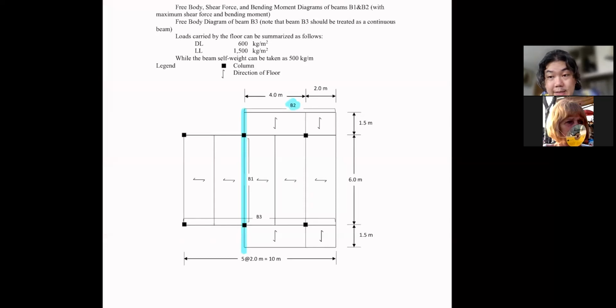Okay, so this is the technique that I wish everyone who takes my class knows. We have a case where this corner is met by two beams. If you look at B2 itself, there is no support directly from any beam, right? And as we speak now, there is no support for B2. So we need to provide two supports for B2.